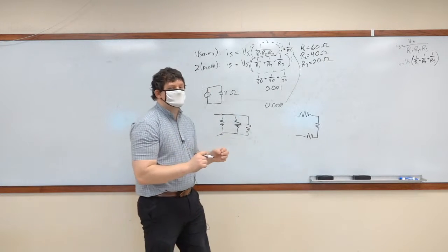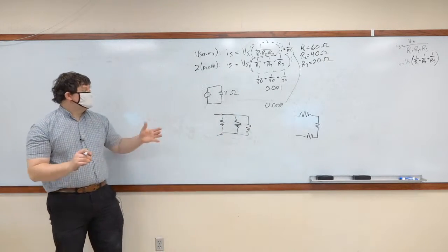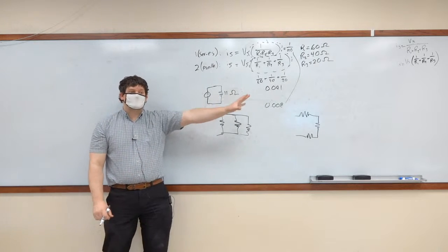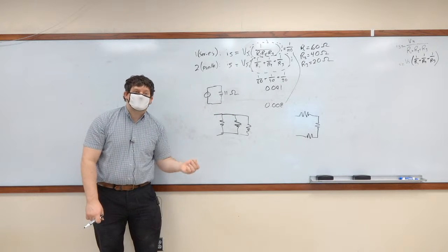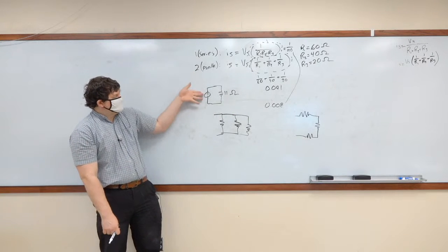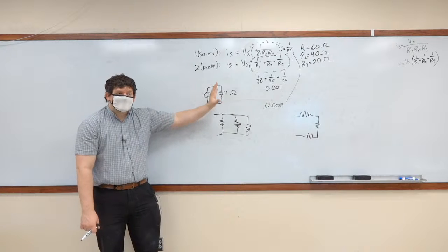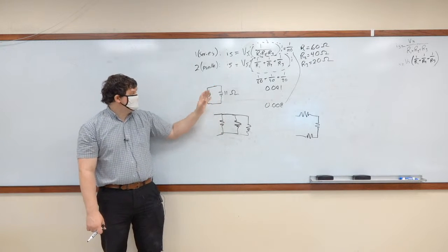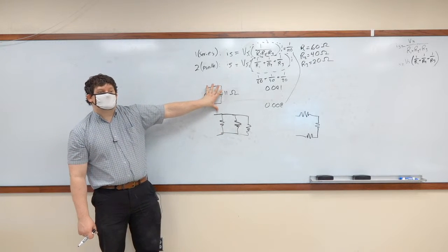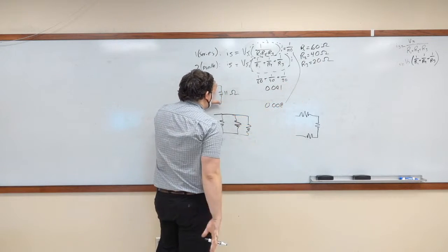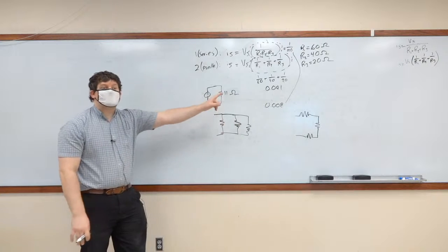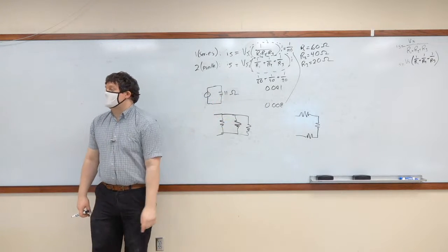An equivalent resistance is basically if you're the battery and you're looking out at the circuit and trying to figure out how much current to supply, you're going to be able to figure that out, and you'll give as much current no matter what that resistance is because it's an equivalent resistance. Okay? As long as whatever to the right of this comes to an equivalent resistance of 11 ohms, your battery will be the same.